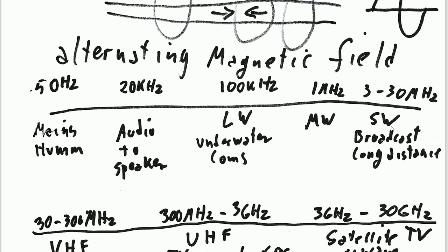Okay, shortwave broadcasting is normally on the ground wave. It follows a little bit over the horizon propagation, but not much. But then the main mode of propagation is it hits the ionosphere, and there are 4 layers. There's the E, the F1, F2, and there's also the D layer. Now on shortwave, you are working with the E layer, the F1 and F2 layer, and the signal bounces off. It's like a massive mirror in the sky, bounces off and then comes down again, and you can easily cover